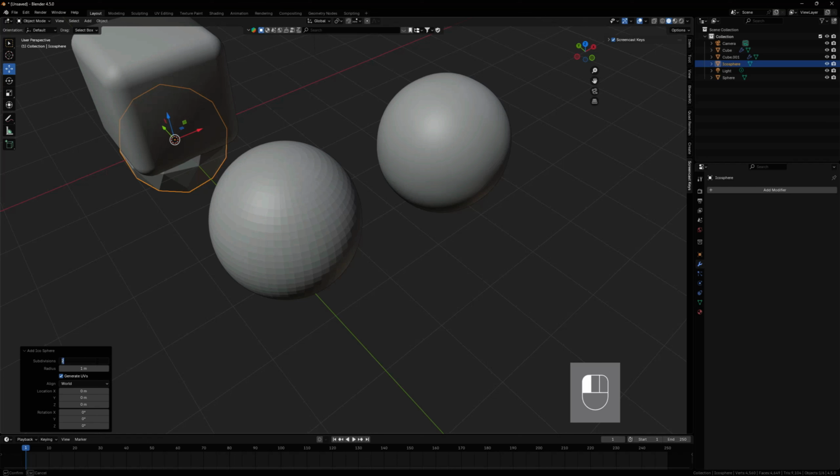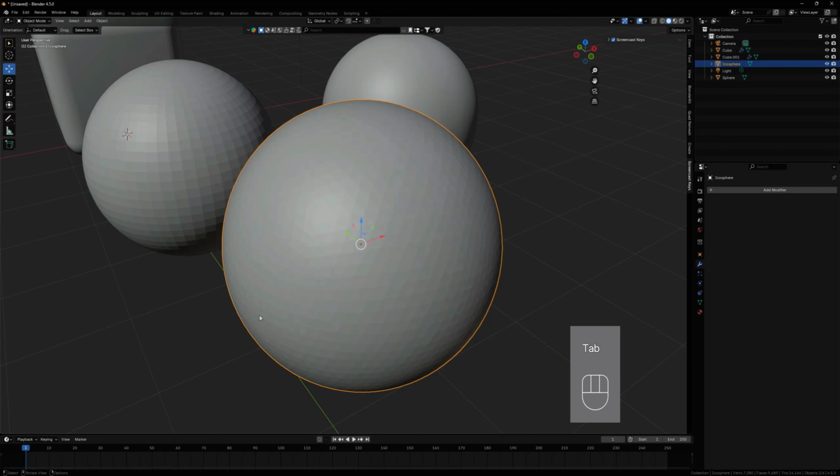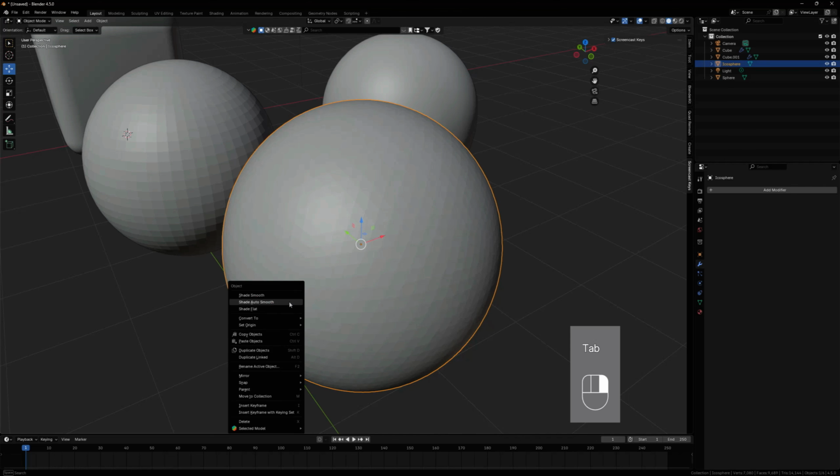If you want a fully triangulated sphere, you can use the presets in the Add menu, such as the Ico-Sphere. You just need to adjust the segments before finalizing the object. I'll set 5 segments, and with Shade Auto Smooth, it will look perfect.